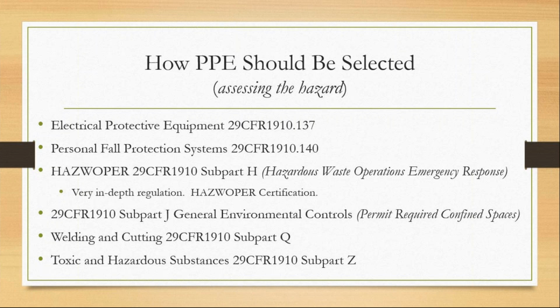You can't just go out and buy a harness and a lanyard and throw it at somebody and tell them to attach off to something up there or on your high reach. You have to have a certified anchor point, and then the lanyard and the harness need to also be certified for whatever it is that you're doing.